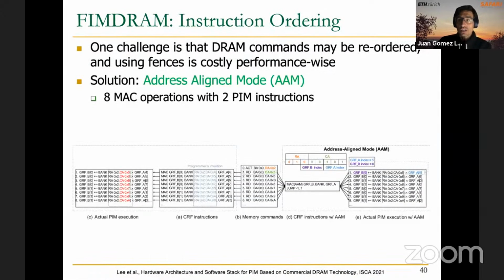Okay, there is one challenge in the design. This is something interesting for you to, if you want to learn the details, go to the original paper by Samsung. But one challenge is that DRAM commands may be reordered. And one possibility of avoiding this reordering of DRAM commands in the memory controller is to use fences. The problem with fences is that they are costly in terms of performance.